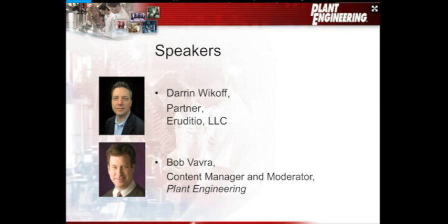And in a failure modes, effects, and criticality analysis, because the style of facilitation is part, problem, and cause, this is going to give me a much clearer picture of what parts present the most inherent risk to the business based on those common business drivers or values. So systems, most significant, then we'd evaluate machines, and then the top 10, top 20% of those machines are candidates for failure modes, effects, and criticality analysis to determine what the spare parts issues are.